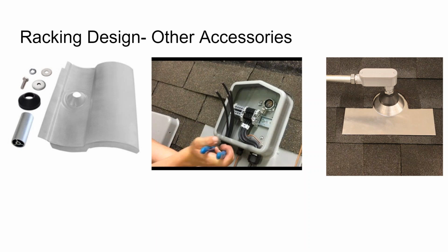So let's see. In estimating the power use for new construction where there's no utility bill, you just have to go off of building averages and construction averages. On the government website, the EIA has building age, building square footage, building location, and building use to help you hone in on that. Or you could start from the electric service panel and calculate hourly loads during a proper energy estimate. I'm going to go through some quiz questions that we didn't get to in this program.